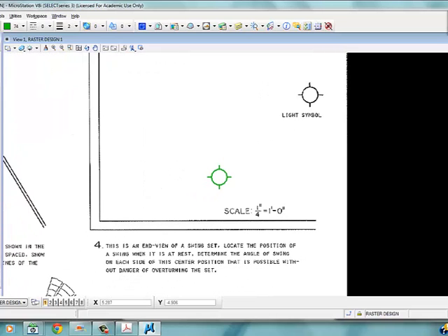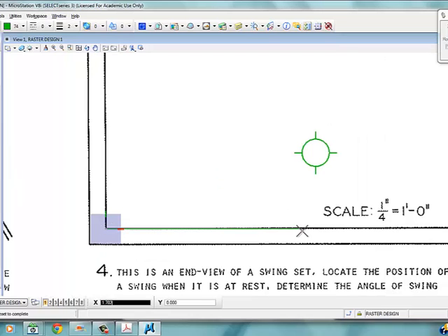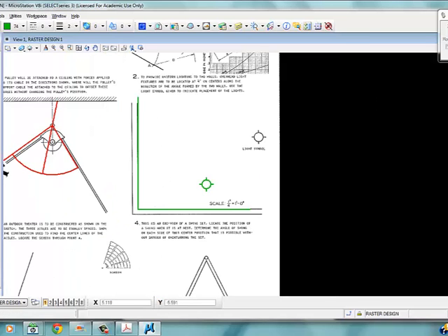Okay, we'll do this one even a little simpler. Take your smart line. We're going to find this corner and just draw a line out. Let's go out a specific distance. We'll go out a distance of 3. It's actually 3 inches. And then we'll go up a distance of 3. So we know these are exactly the same length. Find this endpoint, hit our tilde key, come back to the center, swing the arc. So now we need to find the center point. Again, simply find the center point of the arc, bring it down to the vertex.